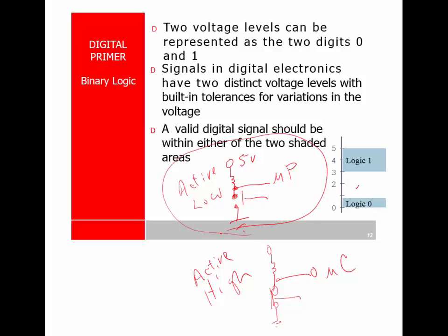In other words, you would want to use this because this here has current flowing right here, all the time until you close that button circuit right there. So this is actually dissipating electricity, drawing battery power, heating up the resistor, doing that when the button's not pressed. When I press the button, I open the circuit, and then there's no current flow. This one here on the top, there is no current flow until I press the button.